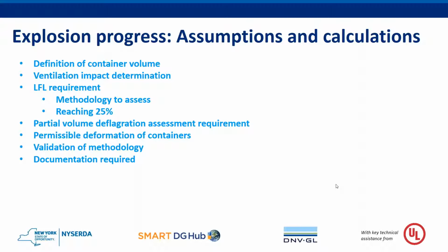Finally, around documentation required, the UL 9540A test report should be submitted in full along with the explosion analysis that goes on top of it. The explosion analysis is recommended to have an executive summary, and that executive summary should indicate who conducted the testing, when it was conducted, what model system it was conducted on, any critical assumptions, and then high-level output information. So a calculation of a hazard zone, a determination of a pressure wave, the size of a fireball, etc. We can go on to the next slide.